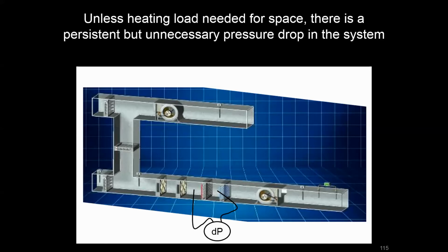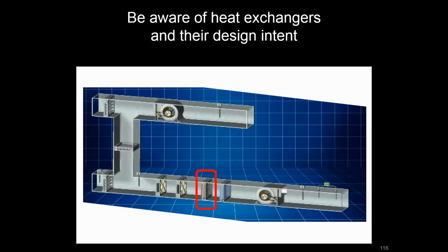So we can actually take the pressure drop across that air coil and plug that into our fan equation to try and find out how much we're paying for that coil. So even if you valve it off, you might have a couple $100 or even a few $1,000, depending on the size of your fan system, associated with the pressure drop of that preheat coil. So there may be conditions where you expect stratified air and you're worried about one corner of your cooling coil being in a freezing condition, but we just really want to think about the purpose of these devices in our system, what job they're doing, and what the cost is associated with that job.